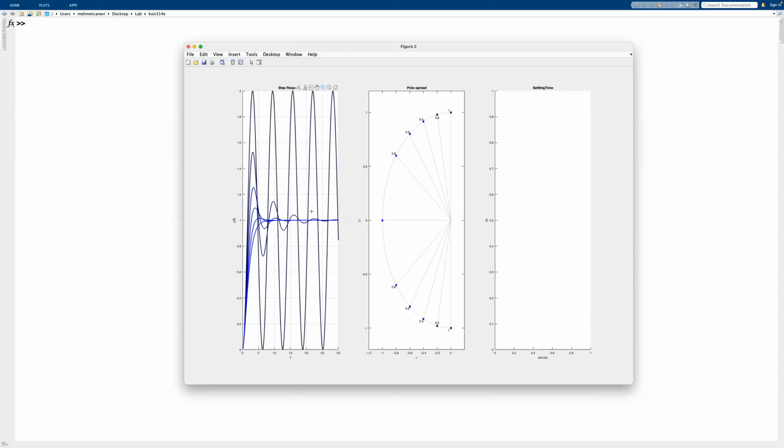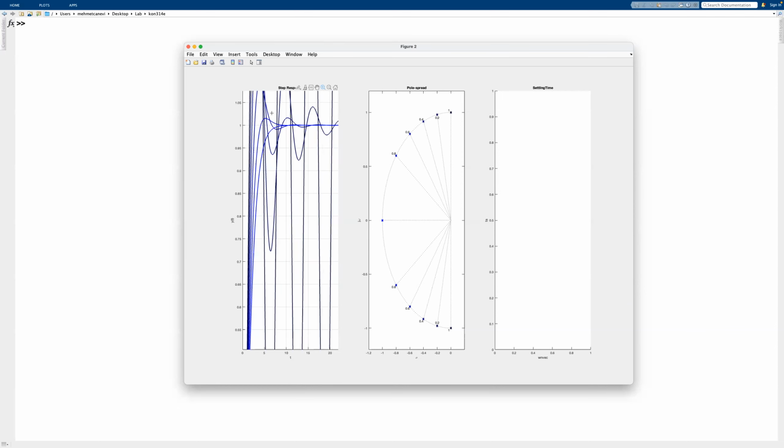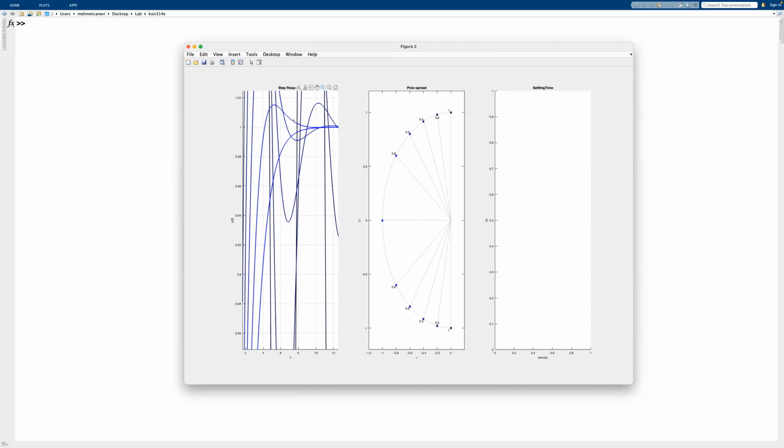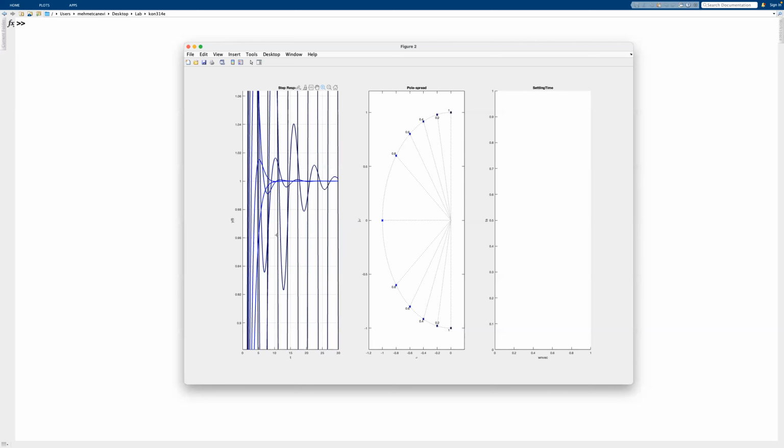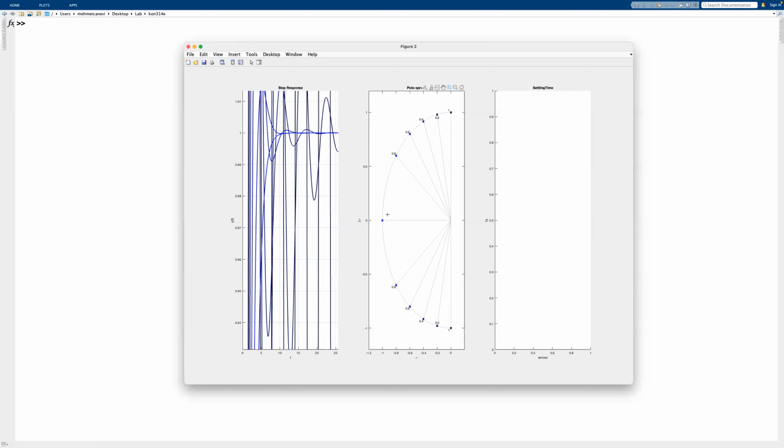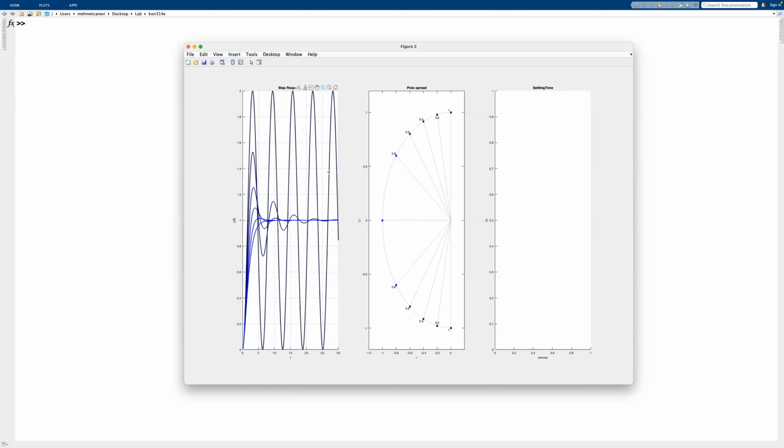And you can see here that the response of such a system is the brightest blue here, and it goes up and it settles down. It never passes through the same point twice. So that's zero overshoot behavior, which we had in the first order system. That's called here critical damp. Of course, we stop at this value here, so therefore we don't see what happens if we increase it furthermore. And we'll analyze that in a moment. But let me bring up the settling time back.